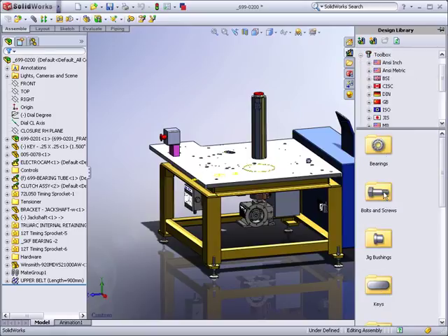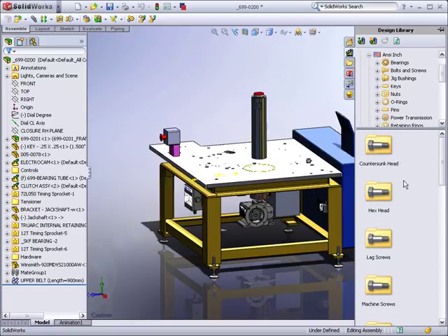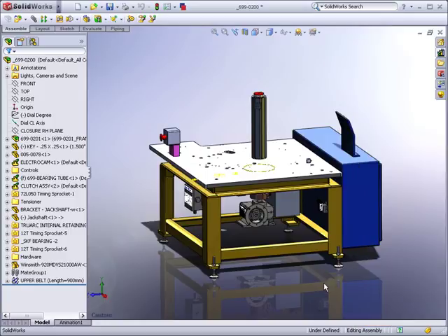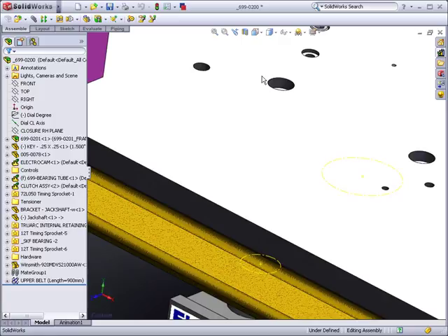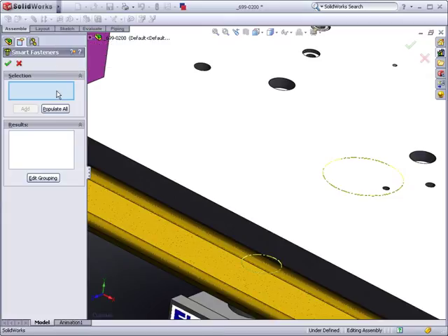Toolbox contains thousands of industry-standard fasteners and parts that can be used individually by dragging and dropping them in assemblies. In this example, we will show how SOLIDWORKS Smart Fastener Technology makes use of Toolbox components to automatically select the correct fastener type and size for holes requiring fasteners. Here, we will add 2 bolts to fasten the support bracket to the table.